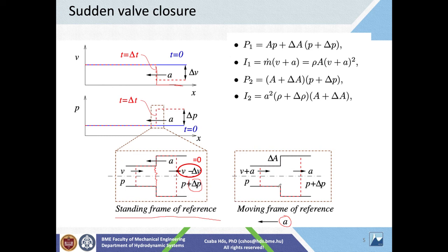So guys, this is standard fluid mechanics. Please have a look in your lecture notes, what you learned from Professor János Vad in fluid mechanics, or if you did fluid mechanics in your home university, then open your textbook. You will find this in momentum theory and control volume concept. What we need is pressure and impulse forces. The pressure forces are always pointing into the volume. The impulse forces are pointing out. This will be cross-section 2, and this here will be cross-section 1. So for example, this is P1 pointing into the control volume, and this is I2 pointing outward.